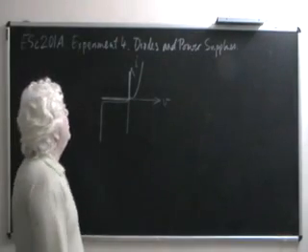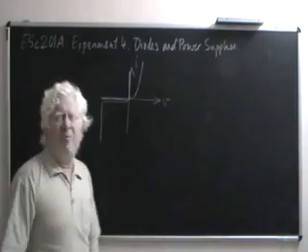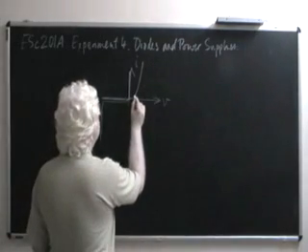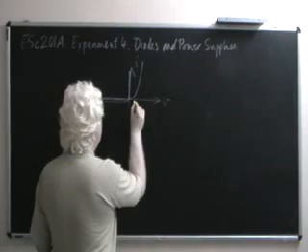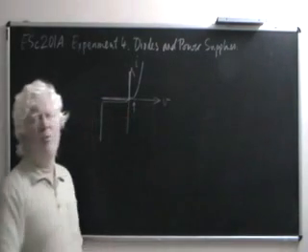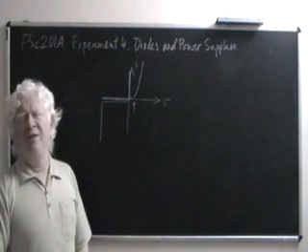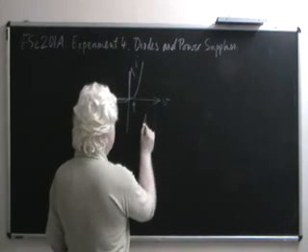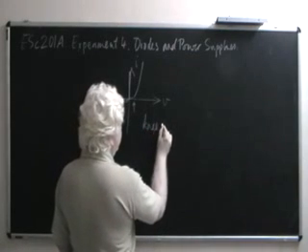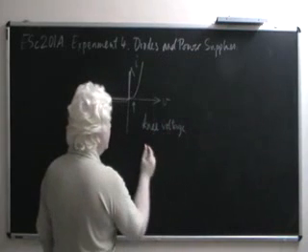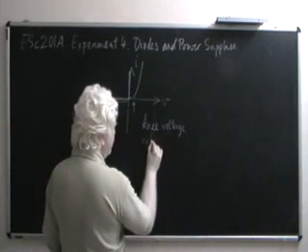Very clearly, you can observe two things about the forward behavior. One, that there is a so-called knee voltage or cut-in voltage of around 0.6 or 0.7 volts. You might even observe 0.8 volts in the laboratory, and it's called, as I said, a knee voltage, technically called a cut-in voltage.